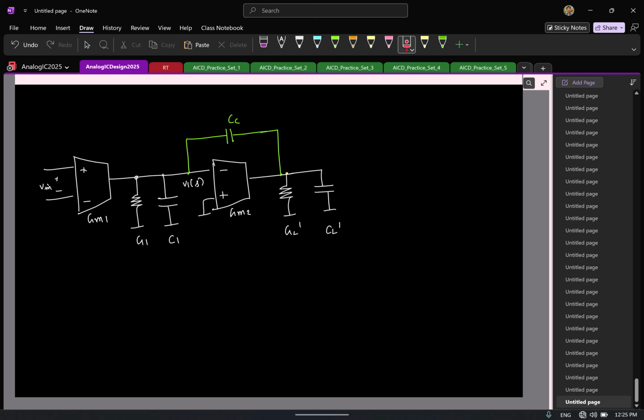Okay. If I make sure that there cannot be a current flowing from, let us say, this side to this, then I will not have 0. Is that clear? Then you cannot argue that I have two currents getting added. And there are a couple of ways in which this can be accomplished. Okay, a nice suggestion, you want to put a diode. Now you have to make sure this is biased properly. So, a simpler thing that is done is the following: you just put a voltage buffer.